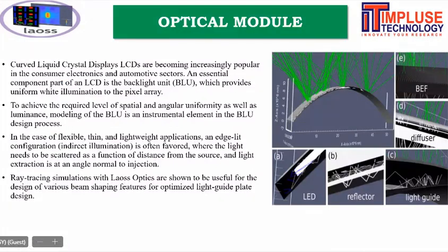In this optical analysis, since it is for ray tracing analysis, either you want to simulate the curved shape liquid crystal related display application, AMOLED, LCD application, or pixel array application. It can be helpful for spatial or angular uniformity or luminance. This is also helpful for flexible thin film lightweight application, edge lighting.